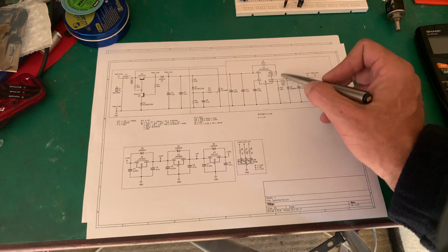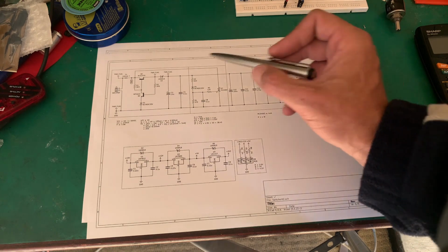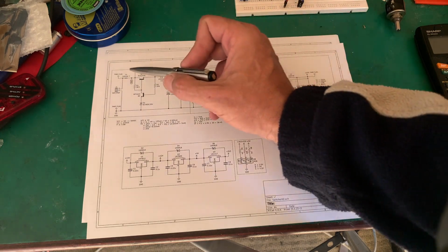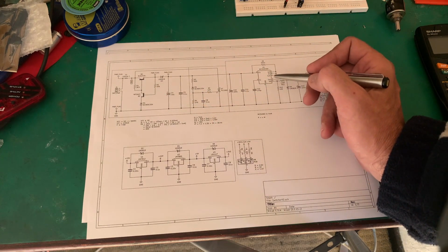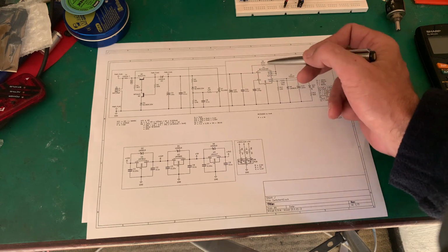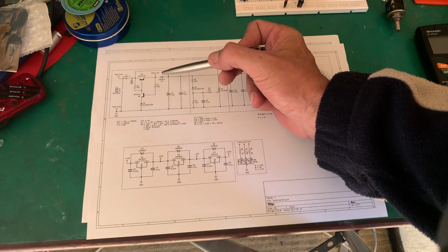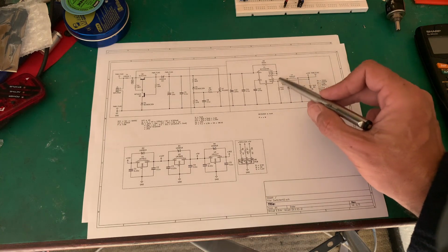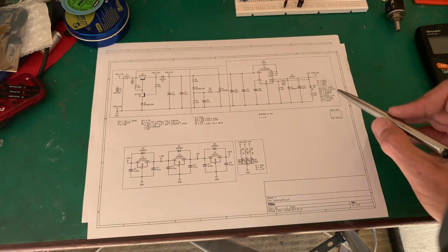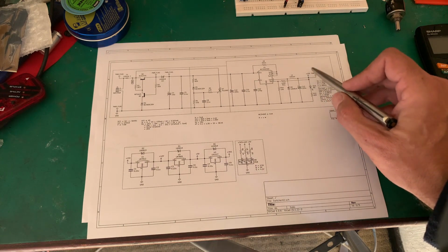We've got this 34063 switcher in a buck configuration. Why we're using this series pass to regulate is because that's 56 volts, and this can only take a maximum input voltage of 40 volts, so what we're doing is regulating it to 36 volts, which is fine. So here we have our buck regulator, nothing fancy with that. We have a little diode telling us it's on, and that generates our 15 volt rail.